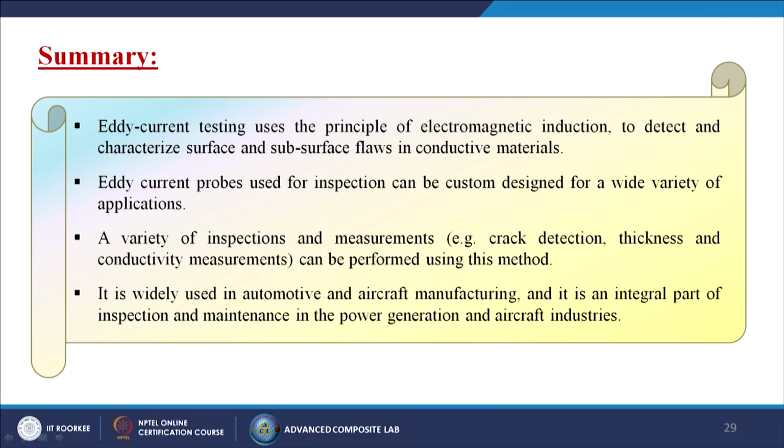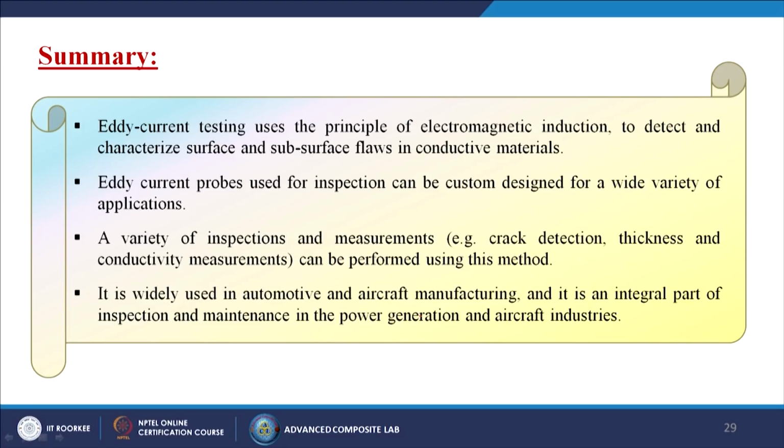As a summary, we can say that eddy current testing uses the principle of electromagnetic induction, developed by Faraday, to detect and characterize surface and subsurface flaws in conductive materials. Eddy current probes used for inspections can be custom designed for a wide variety of applications. It depends upon your shape and size; you can customize your own probe. A variety of inspections and measurements like crack detection, thickness and conductivity measurements can be performed using this method.